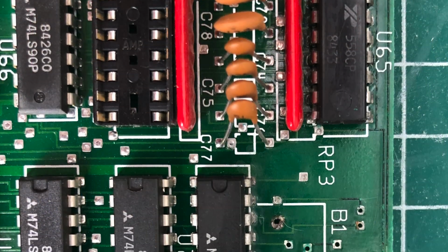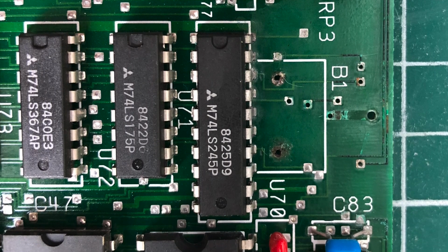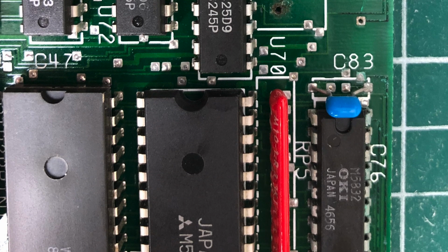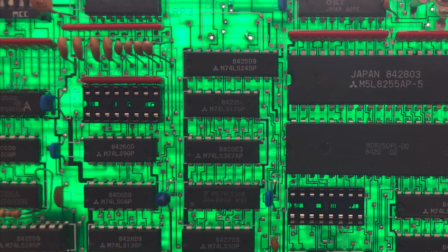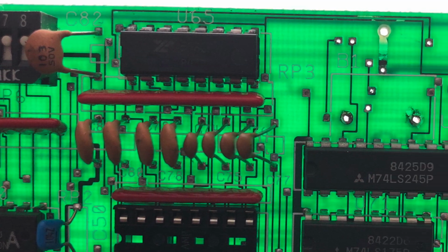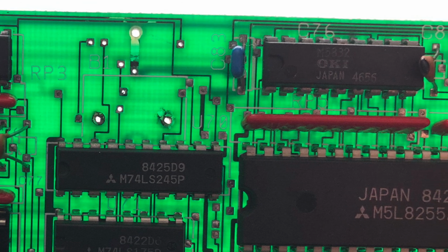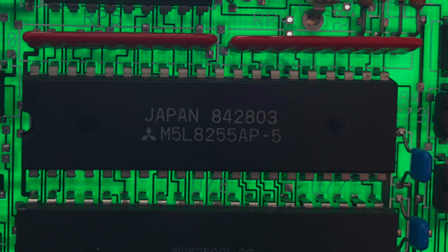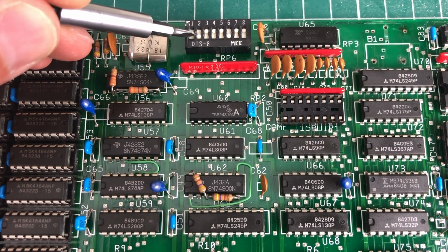To check for bad traces, you need to be able to follow them, and that's not always that easy, especially because there are 2 sides to this board, and oftentimes these traces will go from one side to another. Now, if you place the board in front of a well-lit environment, you will be able to see the traces a lot better, and you will be able to follow them more closely. Now, I've inspected all of the traces here, and I only found one trace that needed repairing, and it was for the game port. So that couldn't explain why the system wasn't finding our additional memory.